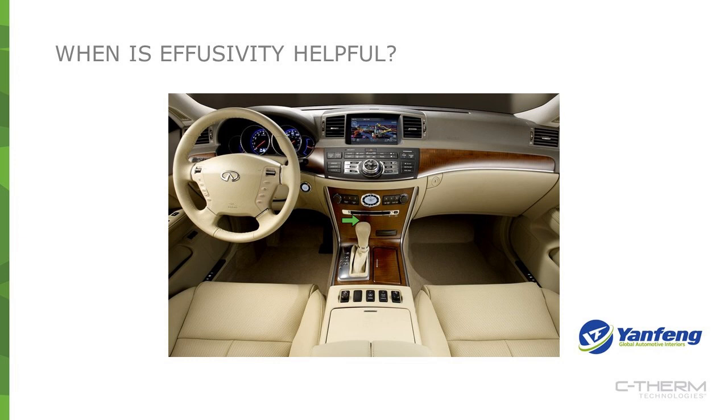So usually as a consumer, we expect to see nice wood paneling, and we expect to see leather seats, steering wheels, etc. But those are terrible materials from a manufacturing perspective, very costly. There's variability within them. They're heavy in terms of weight ratio. So for a lot of reasons, we'd prefer to use a composite or a synthetic version that allows us to achieve a better weight ratio to the vehicle, better fuel economy, and can be manufactured more consistently.